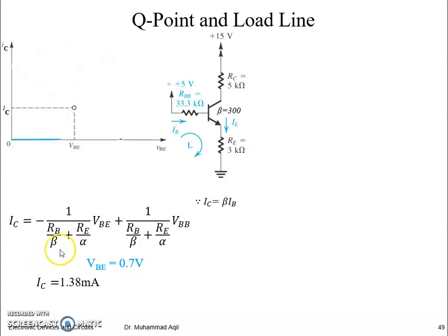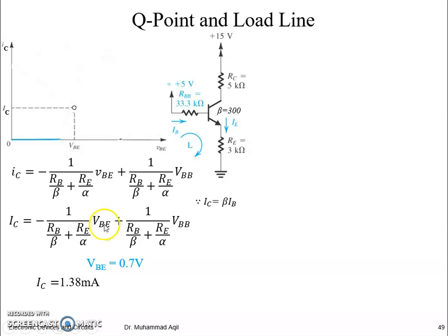To see how the change in VBE will move this point within this axis, the values of IC, let's change this variable to a changeable. So that's why we put a total VBE and total IC instead of just DC values.